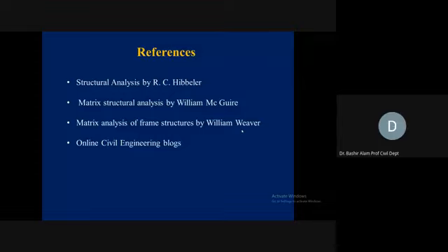Now we put all these member interactions on the member, and the externally applied loads also, and we draw the shear force and bending moment diagrams. And once that is done for each and every member, then we draw the combined shear force and bending moment diagrams.